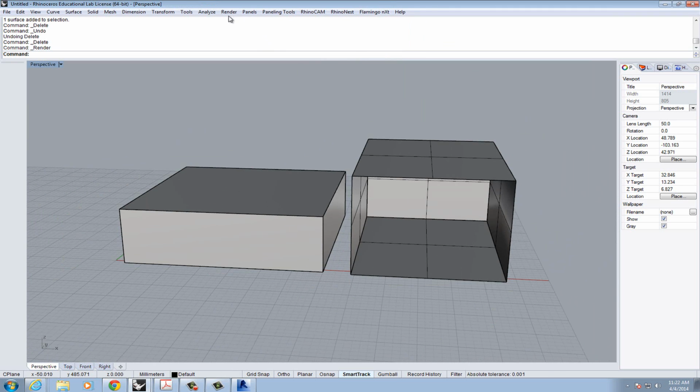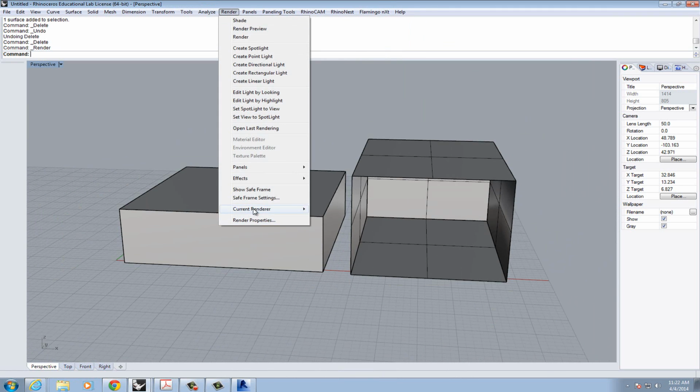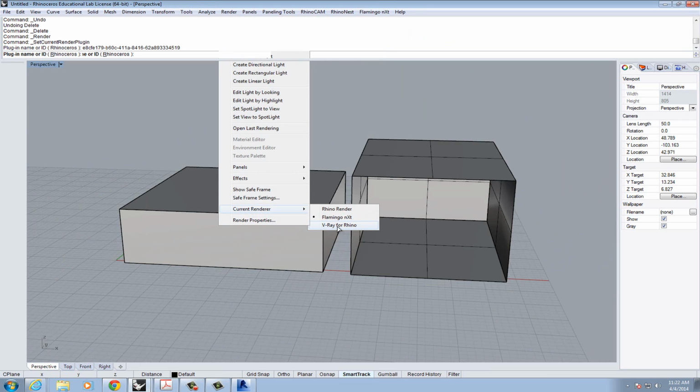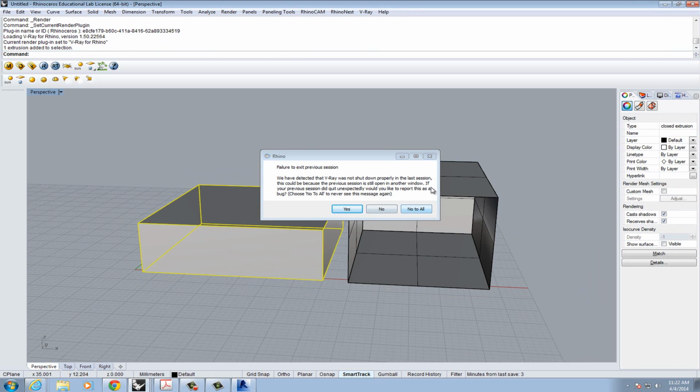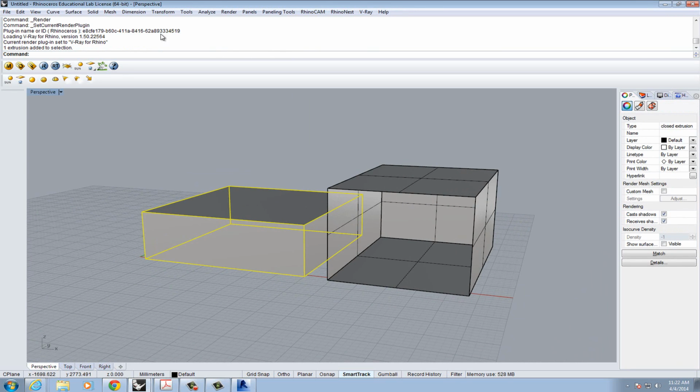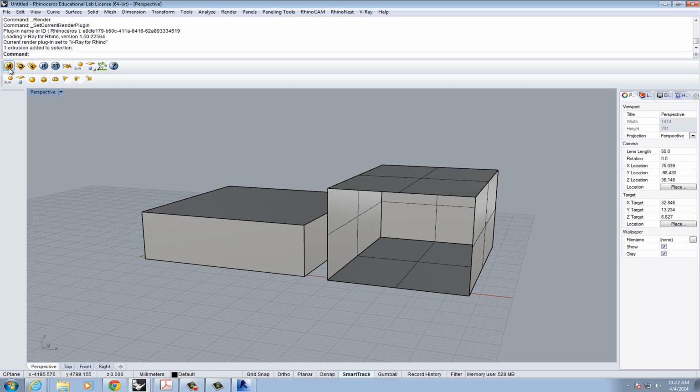And then within Rhino, we have a third renderer, which is Vray, and I think Vray gives you the most control. It's also the rendering platform that I use the most, so I'm the most comfortable with it. When you click it, it opens up these two graphic interfaces for us. Below is lighting conditions, so it allows you to place in a sun. Also different types of light, which you're able to do in the other rendering platforms as well, but also materials